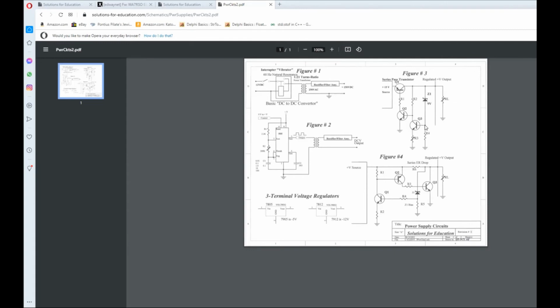That'll come up here, 20 millivolts. And as this goes up 20 millivolts, it will make this transistor, which is an NPN transistor, conduct more. Well, more current flowing through that resistor there causes this guy here to conduct less, because when you're coming off of the collector of one into the other, this acts as an inverter. However, this guy here is not an inverter. As he conducts less, he has less base current, which tells this guy here to not bring this line as close to the power source.